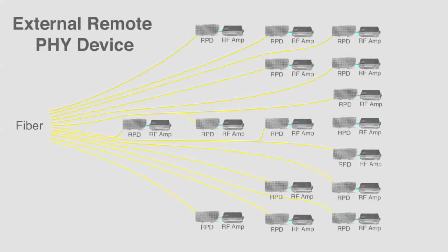Many existing fiber nodes can be fitted with Remote PHY components, typically in the lid of the node. The Remote PHY device uses digital fiber transmitters and receivers and creates the RF digital carriers. The addition of the Remote PHY device does increase the power draw of the node. It's been estimated that the power increase will be around 25 to 30%. This additional power cost will still be less than the savings in the power cost at the head end.